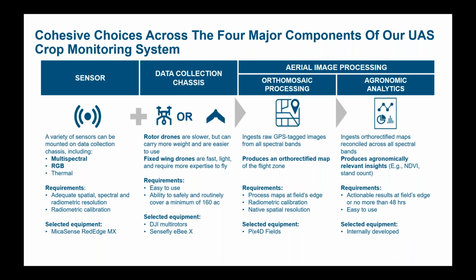along with radiometric calibration. I think, Drew, you really knocked it out of the park on explaining why that radiometric calibration is so good. And really, it boils down to, if we don't have radiometrically calibrated data, it's really hard for my team to build any sort of analytics off that and any sort of automated algorithm off of it. We really had to have really high quality radiometric calibration. And so after doing a pretty large landscape for our multispectral sensors, we selected to partner with MicaSense and run the RedEdge-MXs.